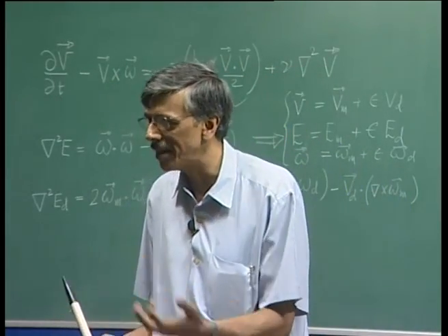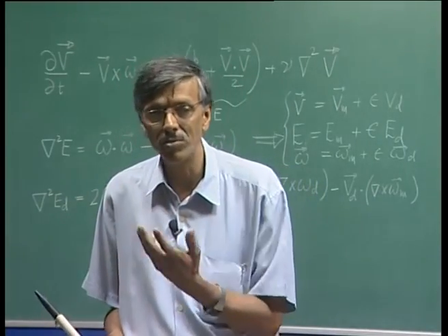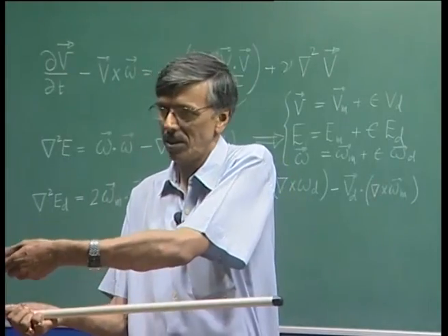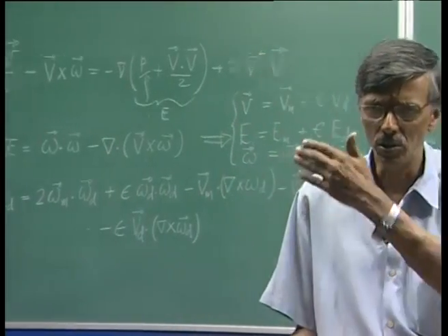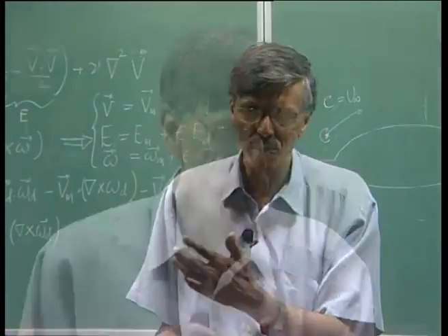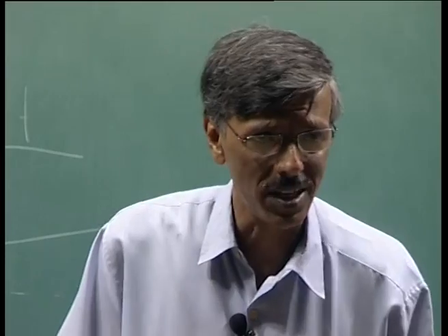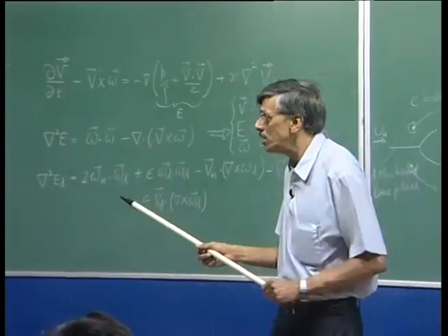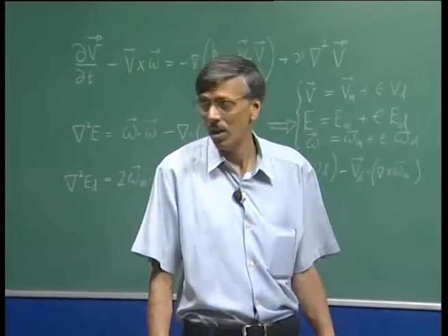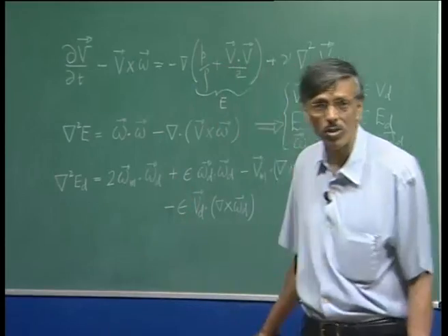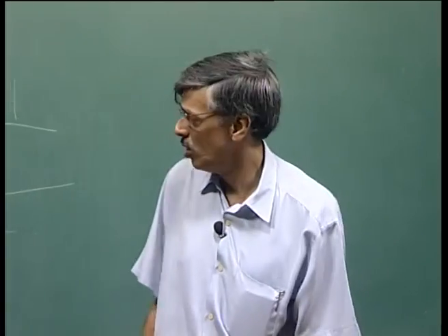In contrast, what we have shown in discussing bypass transition in this part of the course is that we can see in the flow visualization that the disturbance field is two-dimensional, because we saw the dye filaments were lifted up in their own plane. So the mean flow remained two-dimensional. The disturbance field at onset was two-dimensional. Later on there was a lateral spreading, so three-dimensionality would come in, but the beginning of it could be very much true for a two-dimensional flow field. That was also explained in terms of our numerical results, which were based on a 2D formulation.